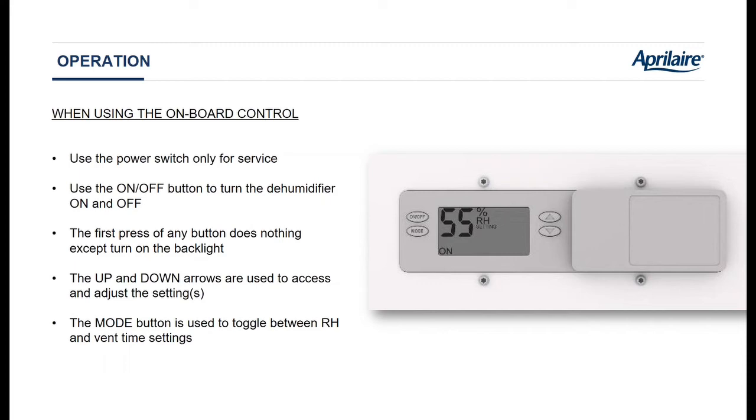The dehumidifiers come with an on-off rocker switch. It's located on the same end of the dehumidifier as where the power cord enters the unit, right above that power cord. If you plug in the unit and the screen doesn't power up, even though you're pushing the soft key labeled on-off on the user interface, it's not DOA. Just make sure you've got that on-off rocker switch hit to on.